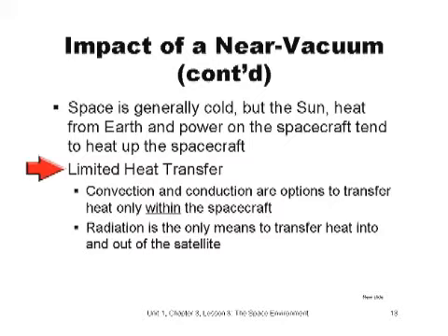If there's a fan or air conditioner, air molecules are flowing over your skin, carrying heat away through convection. You're also radiating heat away from your body by electromagnetic radiation. If you hold your hand close to your cheek, you'll feel heat coming from your face. This is electromagnetic radiation. In space, the problem is that the spacecraft can't touch Earth, so conducting heat out of the spacecraft isn't possible. In addition, there are very few molecules in space, so convection doesn't work.